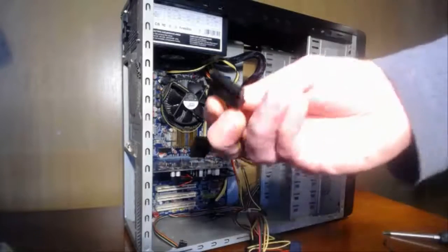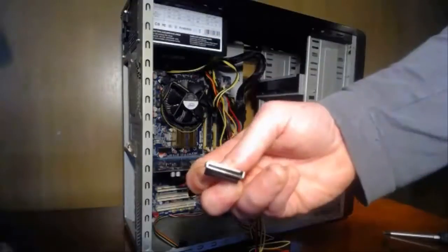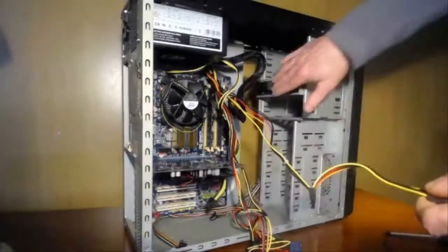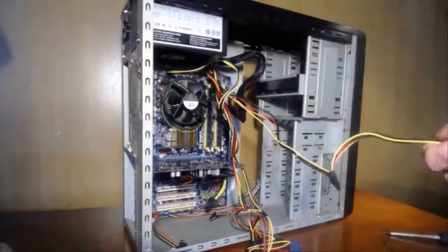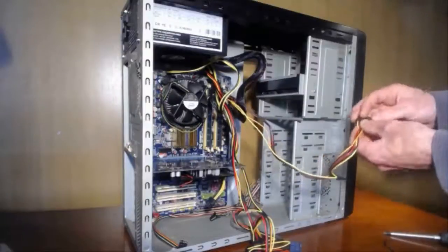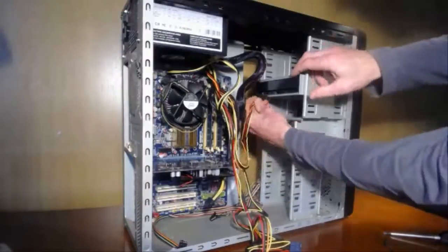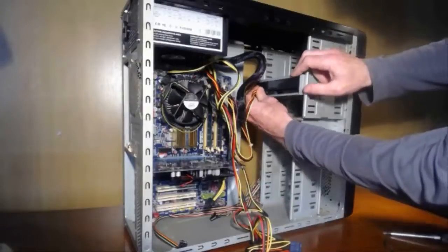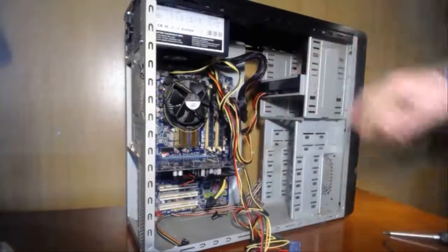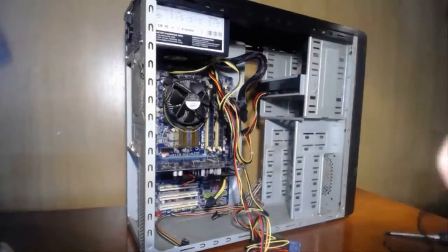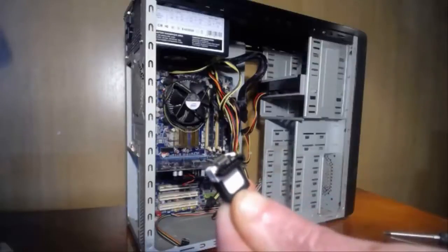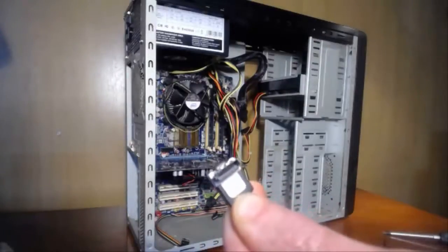SATA cable, and it's keyed also. See it there, it looks like the shape of an L. That corresponds to the power in the DVD player. And all you do then is just plug it in to that actual spot. And that's your power connected to it. Then take your data SATA cable and connect that to the DVD player, which is also keyed the same way,